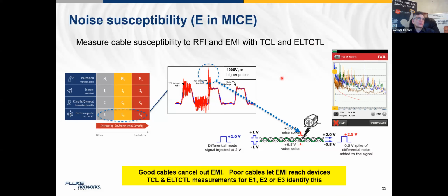A cable that does not have a good quality could be more affected or more influenced by electromagnetic interference. So if there is a motor or an engine or machinery or other waves that could influence that cable, and that cable is not properly dimensioned or is of lower quality, this could influence your data again. You will have wrong signals, wrong data going through your control panel. Machines will stop or not work correctly.